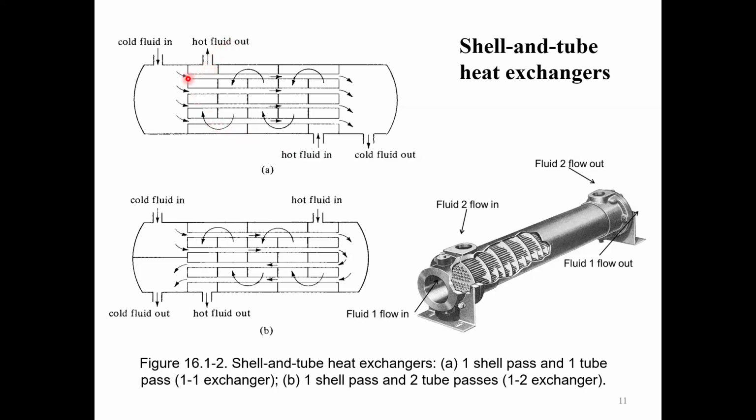Likewise, if sedimentation can happen and it can plug the tubes quickly, such fluids preferably go through the shell side.